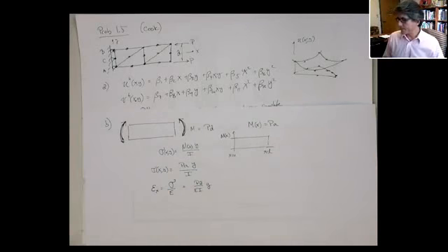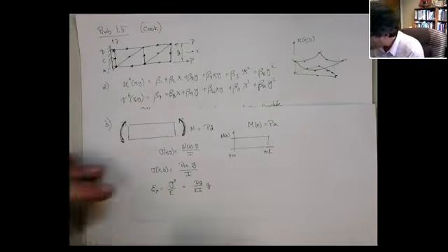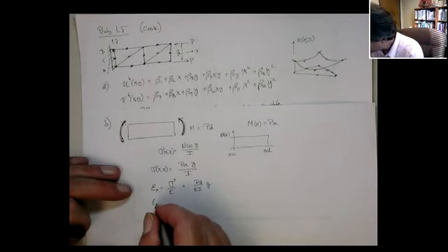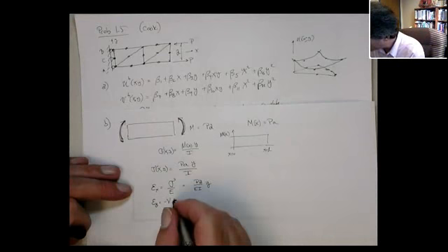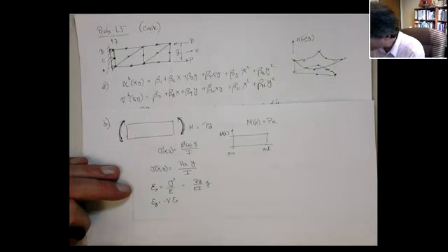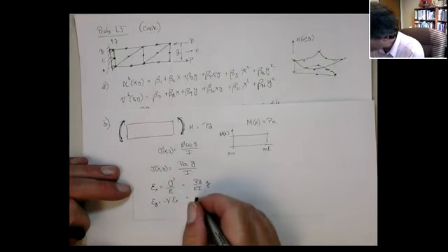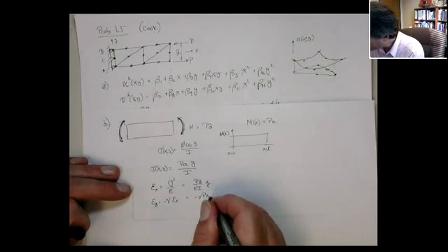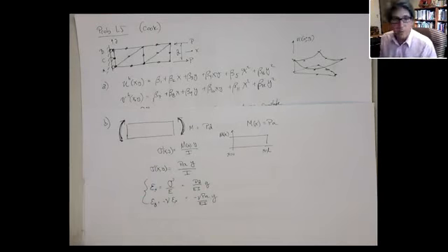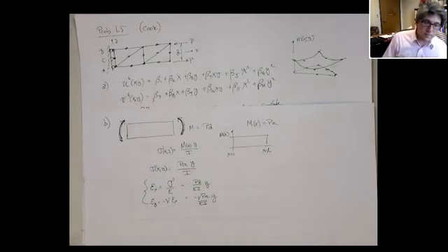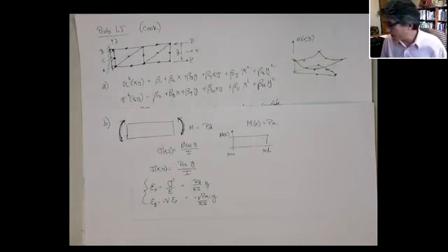Okay? Now, the lateral strain is going to be, through Poisson's ratio, minus nu times the longitudinal strain. So that gives me minus nu PA on EI times y. So again, the strain field for the perfect bending is a linear polynomial.